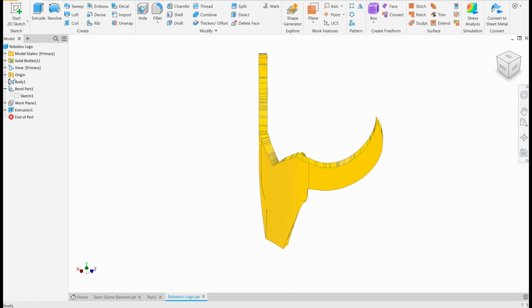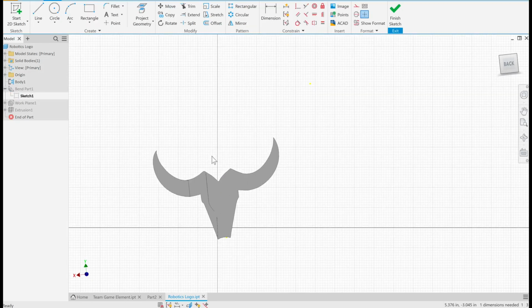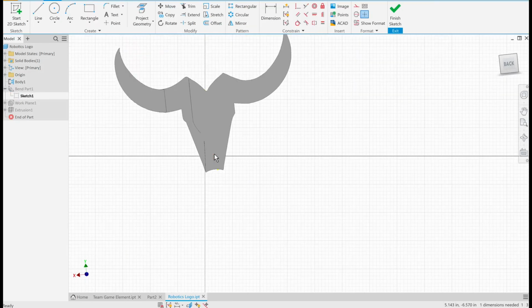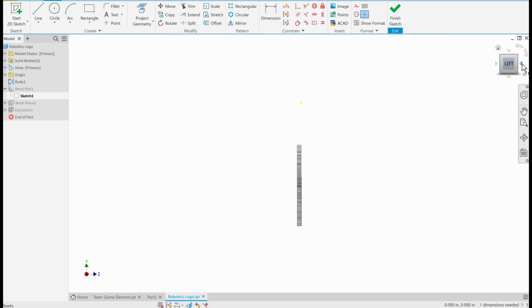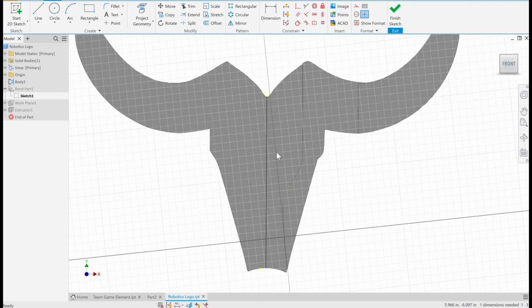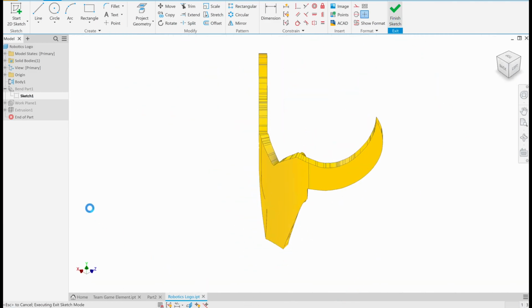If you remember, we made a logo in Fusion 360. We're now going to bend that logo. First thing you want to do is open up that logo in Inventor. I already have it done here, because I'm a bit lazy and I didn't want to do the entire process again. But let's start. First, create a sketch on one of the profiles, and draw a line from the center of the dip to the center of the dip at the bottom, because we need to use that line to actually bend the part.